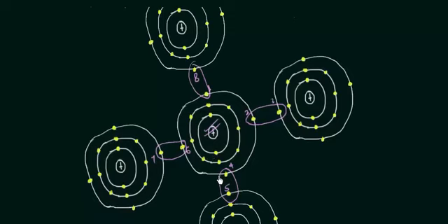This structure we are going to use in this presentation also, but this one is a little bit bulky, so I'm going to eliminate a few things that will make this structure simple. I will not represent the nucleus and orbits like this, but I'm going to draw a circle, and this circle will represent the atom. In this case we have a silicon atom, and to represent it I will write Si inside the circle. If you want to make the atom for germanium, draw the circle and write Ge inside it. Now let's see how we have to represent these 4 covalent bonds.